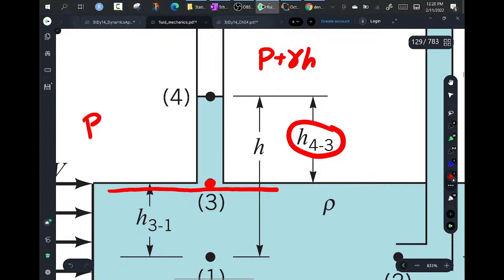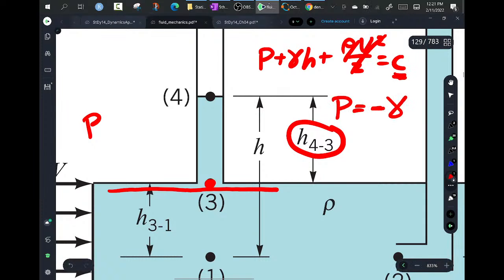Again, if you had no movement, then you could say this is a constant, you could say this. So in fact, the fluid statics and fluid Bernoulli's equation, they have the same element in them. Meaning, I guess you could say the manometer equation is a subset of Bernoulli's equation.